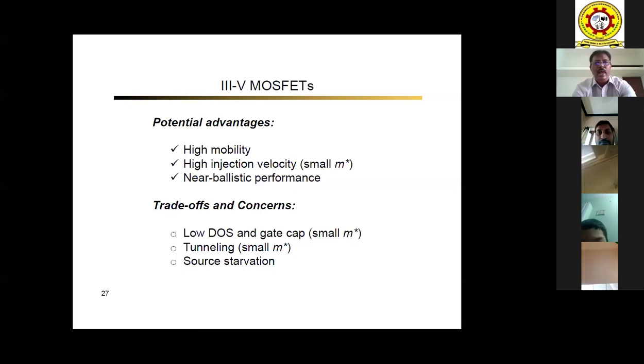you can assume it's happening in a long channel, but definitely not in a short channel, because as I said, surface scattering is happening because of the lateral field, because of the field applied at the gate, right? Your electron is getting attracted by the excess positive gate voltage and it collides with the silicon SiO2 interface. These are the collisions happening, right?